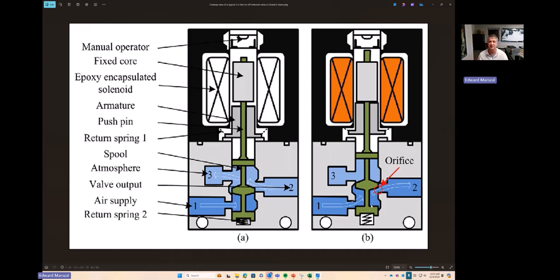They drained the system out and repaired the air dryer, but this equipment was wet for so long that as soon as you drain the water out and put air in, everything corroded and rusted over, and every solenoid valve in the entire plant failed because of all the corrosion that was generated by taking the water out of the instrument air system. So, whose data do you trust?